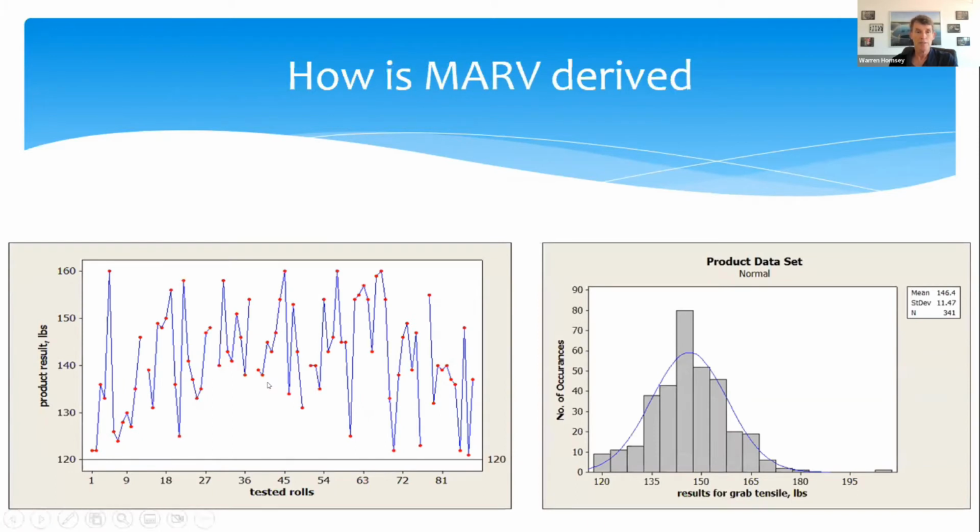And this graph essentially shows the type of variability that you can see in a production run over time. So this is rolls tested. This is not rolls manufactured. This is rolls tested. And you can see the big variability in results during the manufacture of these materials. So don't think that the stuff, because it's man-made, is exactly the same over and over and over again. There's things like needle wear that come into play, polymer quality, and in GCLs, the interaction of the clay with the needles, and so on. So be aware that while everything's done to make a very uniform product, there will be variability in this material during manufacture, and the material that you send out to site will be variable.